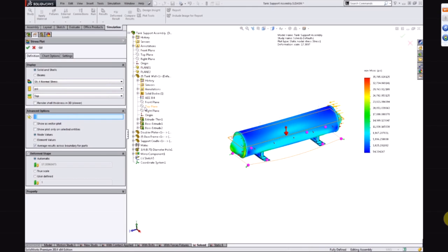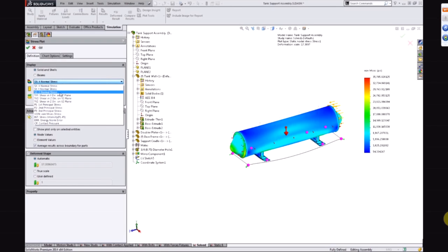If I had some angled plate that I wanted to measure stress relative to, there's a reference there. So I can look at stress in X, Y, Z and shear stress about those three directions. No problem. One of the challenges is that the net stress and overall assessment of stress in the model can only be made by some combination of all 6 of those states.